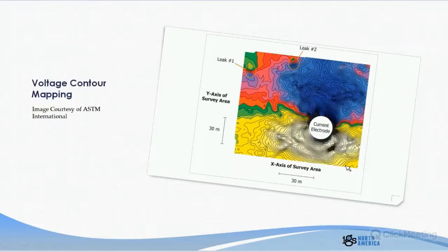So this big square represents the entire survey area. Your current electrode is coming in right here. And what the current electrode does is it polarizes the entire survey area because it's being measured by a dipole. So the entire top half will be negative in general, and the entire bottom half will be positive in general. And that's simply because the dipole is walking this way, backwards and forwards, throughout the survey area, and it's always pointed toward the top of the map. So as it's walking this way, it's measuring positive voltages, and once past the current injector, it starts registering negative voltage values.